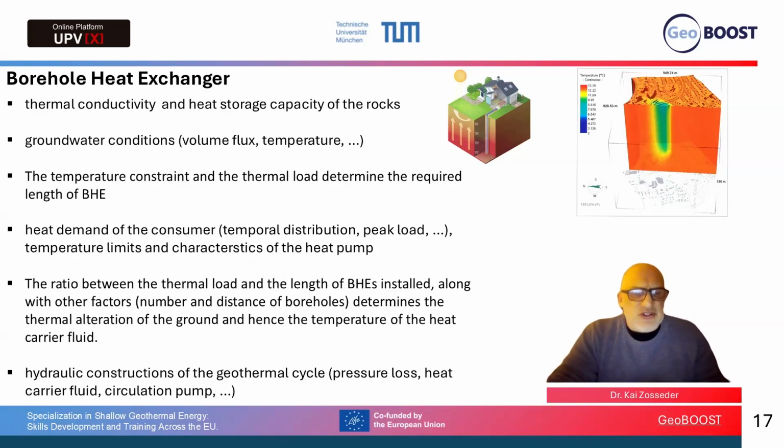So these are also factors to determine the thermal alteration of the ground and hence the temperature of the heat carrier fluid. It shows how the temperature goes down in the underground during the heating period and then how it is recovered after the summertime again. What is also important are the hydraulic constructions of the geothermal cycle: what is the pressure loss, how the heat carrier fluid behaves in the pipes, what we need for the circulation pump, and so on. This must also be very well designed.